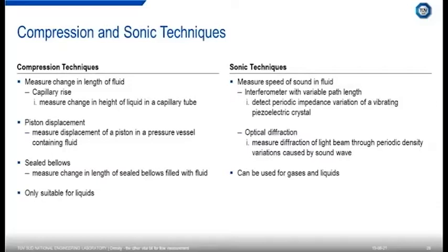You can measure the displacement of a piston in contact with the fluid in a pressure vessel, or you could seal the fluid into a bellows and measure the change in length of the sealed bellows as you compress the bellows or expand it. These techniques, of course, are really only suitable for liquids, but they can be used across wide temperature and pressure ranges.